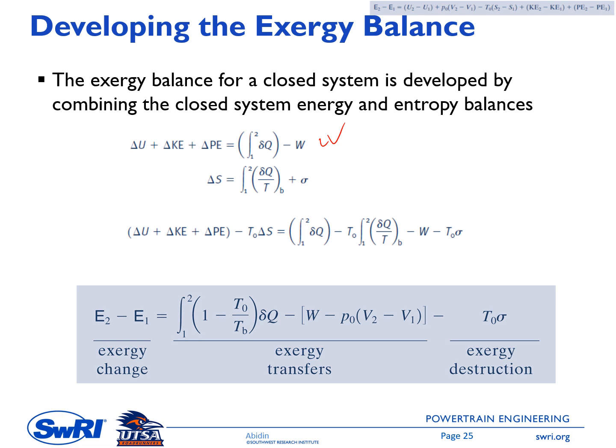The next equation is the entropy balance, from chapter 6, delta S. Here the change of the system entropy is balanced by the heat transfer that happens at the boundary with the temperature T here, where T is TB, plus the entropy destruction sigma. That's why you know the term isentropic. Isentropic means that delta S equals 0. It's just to refresh our memory.